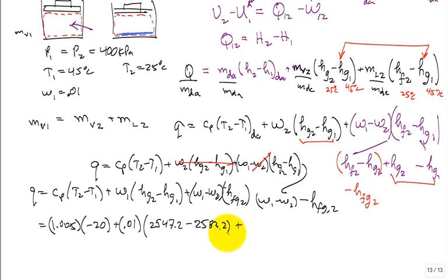and then omega 1 minus omega 2. I calculate omega 2. It's in your skill set. You find that omega 2 is 0.0022. Now I know that these numbers are hard to see, but it's like 0.0100. See, that's 4 digits. This is 4 digits, okay? So it's like 100% went to 22% and 78%. So what's 22%? 22% of the vapor that was in there stays vapor, but 78% of it turns to liquid.